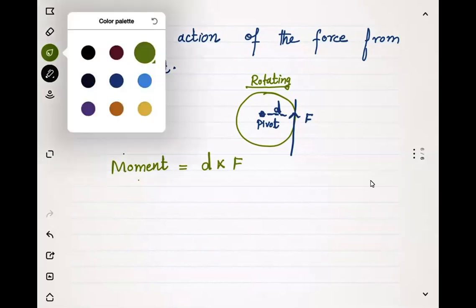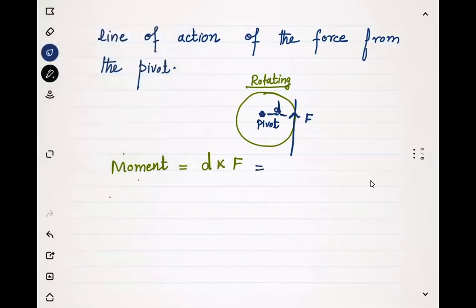The unit and base unit of moment would be, unit of force will be Newton meter. As you see, force is in newtons and distance is in meters. However, this Newton meter cannot be written in terms of the energy unit, that is joule, because joule is the capability to perform work. Basically, the rotation and the work or energy cannot be added. So by principle, the rotation and the energy are two different quantities. However, you can ask why their base units could be same, or why their formulae are same. Their formulae are not same exactly.